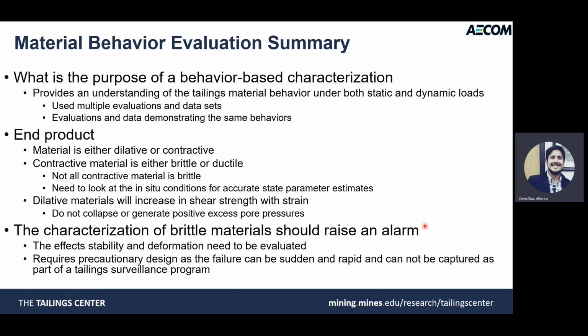And really, in terms of design, you should use a precautionary design in which you should assume that these materials will trigger regardless of the trigger mechanism, and then design a buttress or something that can hold these materials in the event of liquefaction.